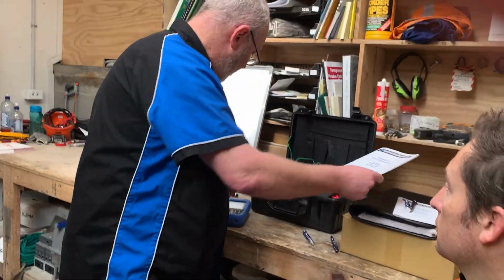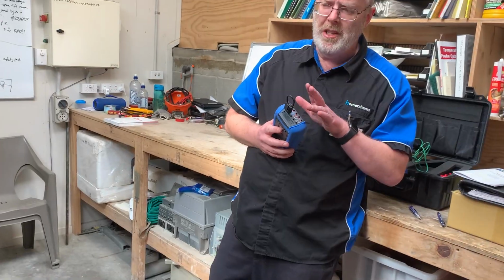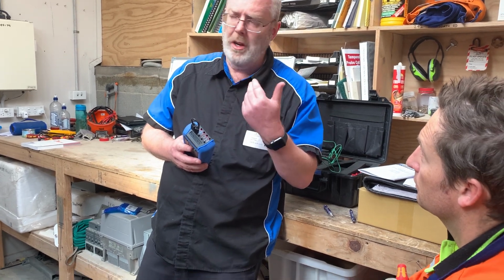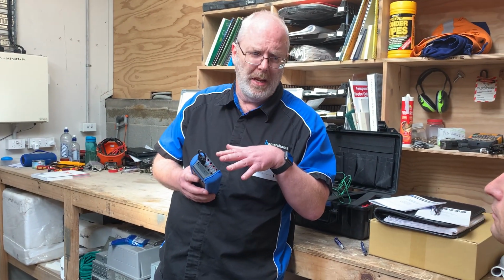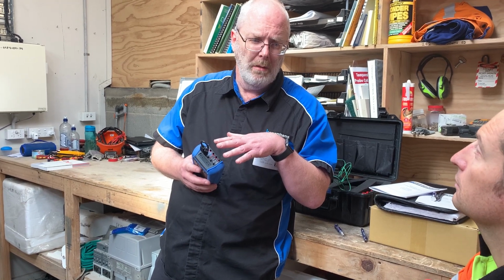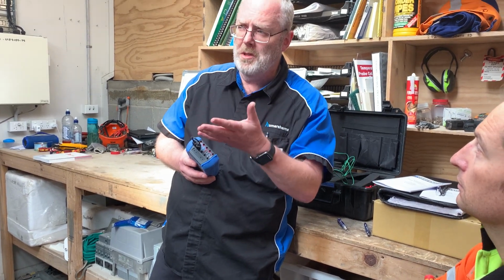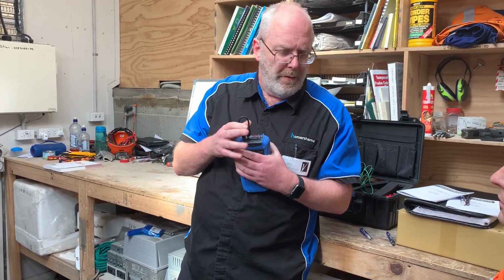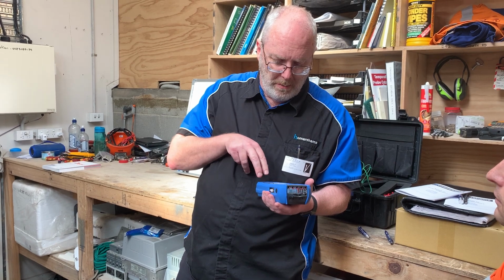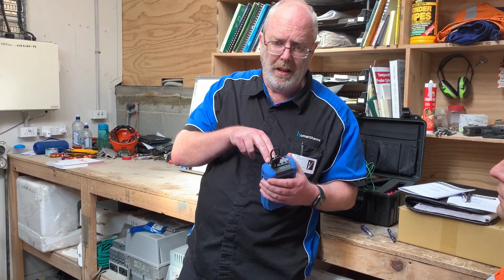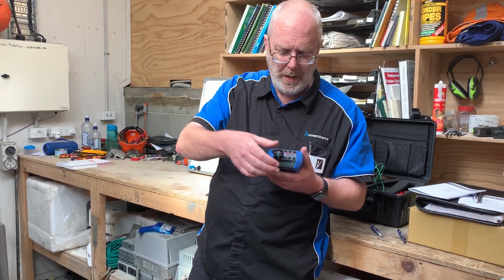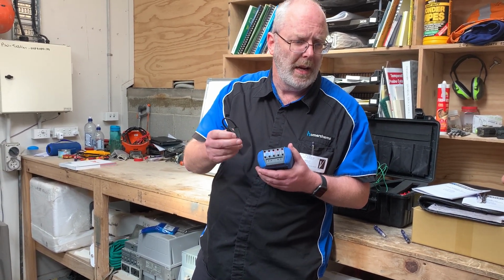There's also, by the way, if you get really stuck, go back a step. All the inputs are protected for up to 30 volts. So if you're working on a loop circuit, don't panic too much about getting it wrong and cooking it, because they're protected up to 30 volts. On a loop system, quite often I'll go, was it there or there? And if you were testing it the first few times, you could put a multimeter on and see, am I getting a variable voltage, or am I getting 24 volts that represents that current? Okay, I'll send you the photos of common setups.